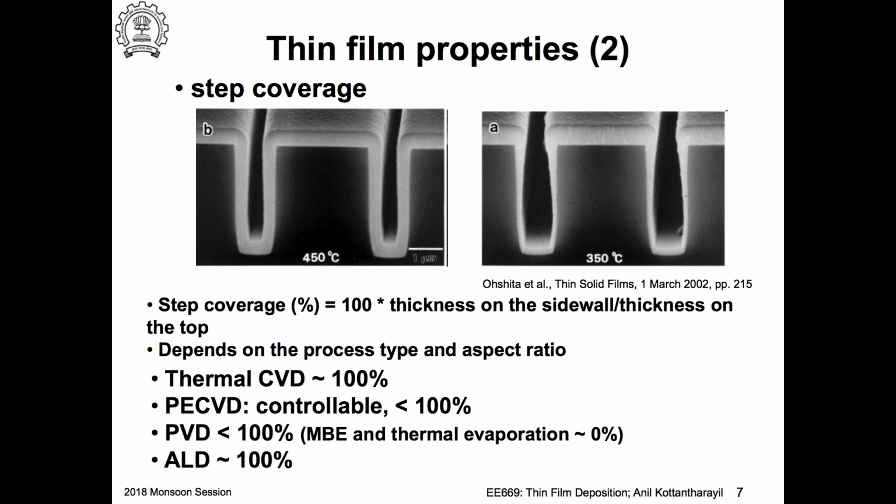Okay, not like this. Very important consideration. Now, how do we define the step coverage? So the step coverage is nothing but thickness on the side wall divided by the thickness on the top. Okay? Ratio of this thickness to this thickness, and you multiply with 100 to get the step coverage in percentage.